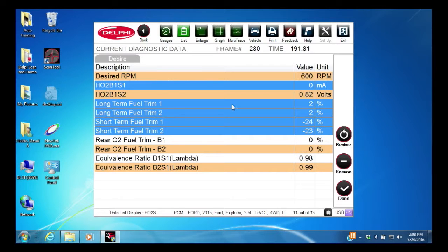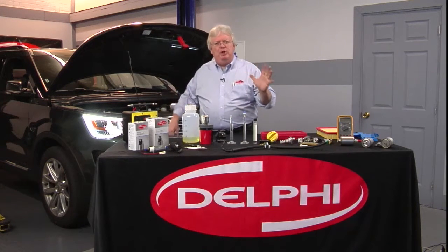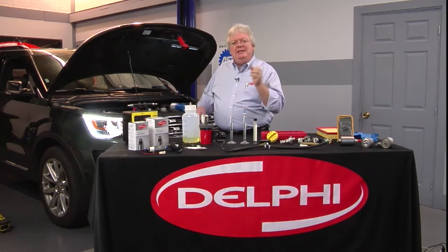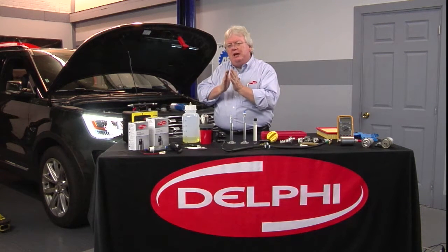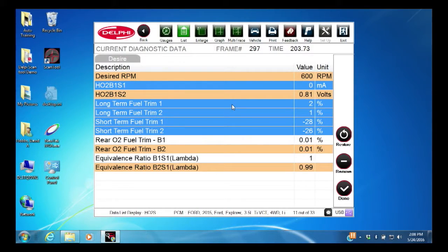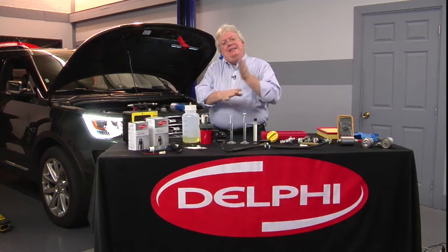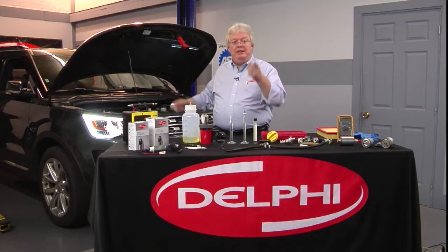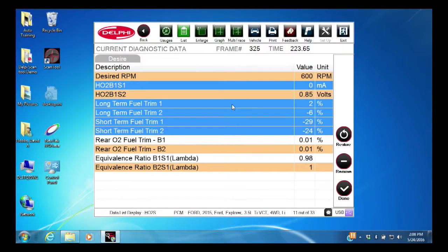So the O2 sensor is going, there was not a whole lot of O2 left over. We're rich. The computer says, let me lean those injectors out by narrowing the pulse width of the injectors, thanks to the propane. So we've got a really nice system going. This is delayed. There's actually a data PID you can see on delayed action or reaction with fuel trim, and that's a bidirectional PID on some scan tools that you can turn off and see an immediate response when you turn the propane on. I'm getting a good response now. If we continued doing this, driving down the road, we'd probably set a code for a rich mixture, both banks.